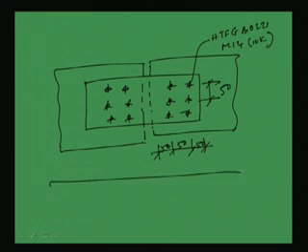So with this I think it will be clear to all that the bolting design and analysis is very easy, because it is almost similar to the riveted joint. The only difference is that the nominal diameter is considered in case of bolted joint, and in case of riveted joint we used to consider the gross diameter, which is the nominal diameter plus the extra diameter of the hole.